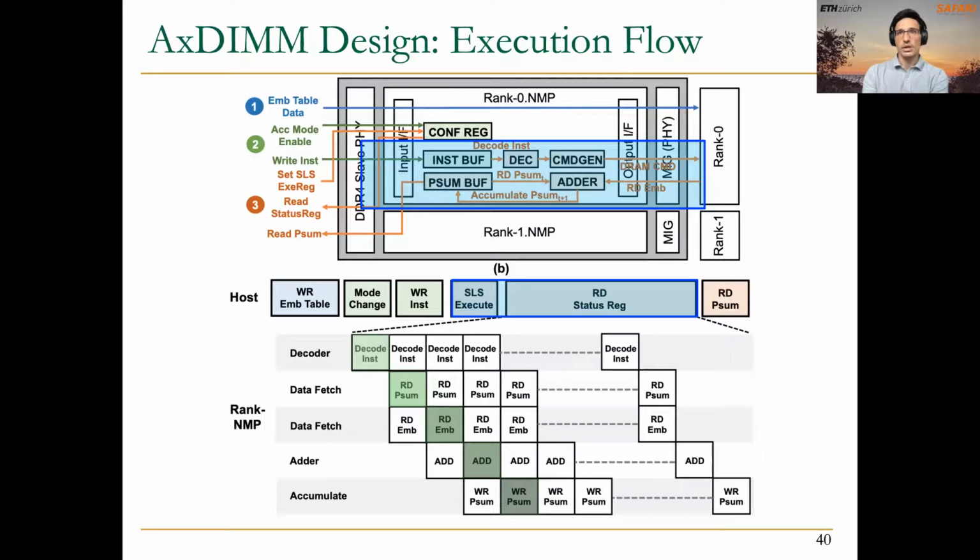During that time, the CPU is also checking all the time this status register, which is one of the configuration registers, and that is the way for the near memory processing unit to signal the host processor when the execution of the near memory processing kernel has finished and all these instructions have been executed.